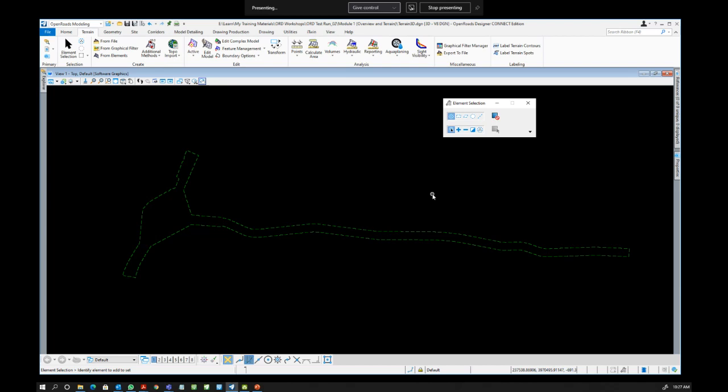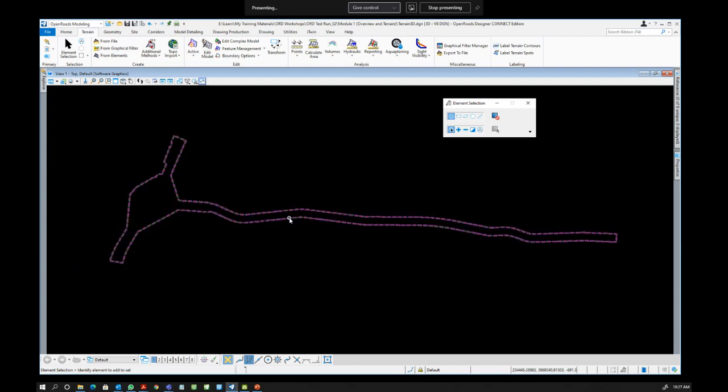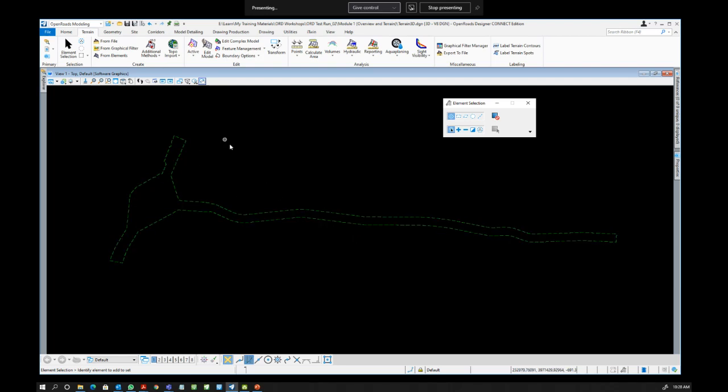And if, for instance, every time you reference or open this file you want it to zoom into this area, in OpenRoads we have this setting called save settings. By the way, you don't need to worry if you're doing some edits and did not configure anything in the settings of OpenRoads. The file is auto-saved, saved by default. So you don't need to click the save button as you can see here above.